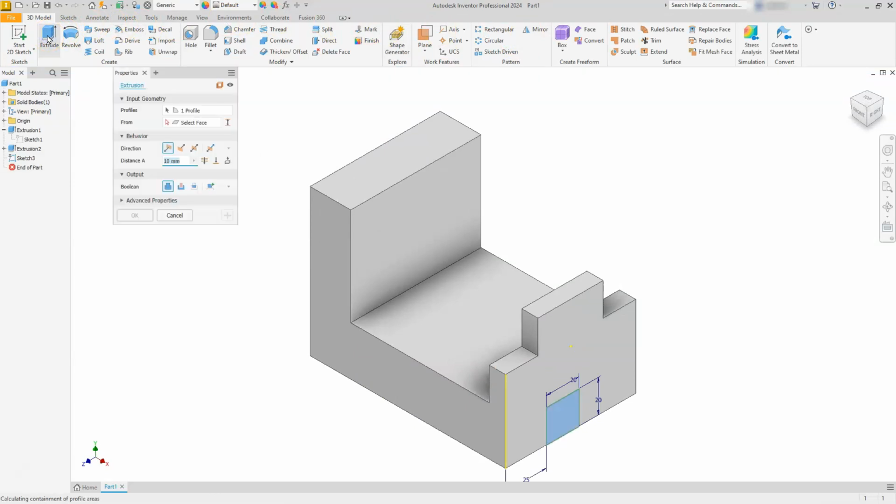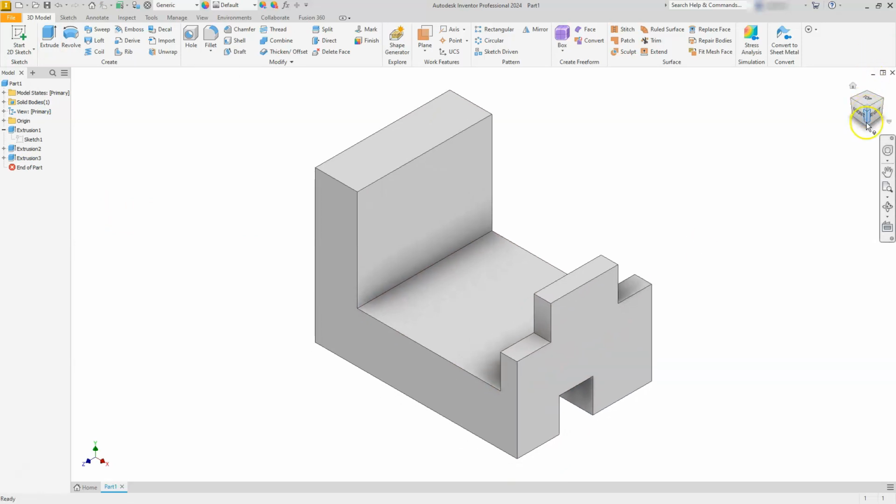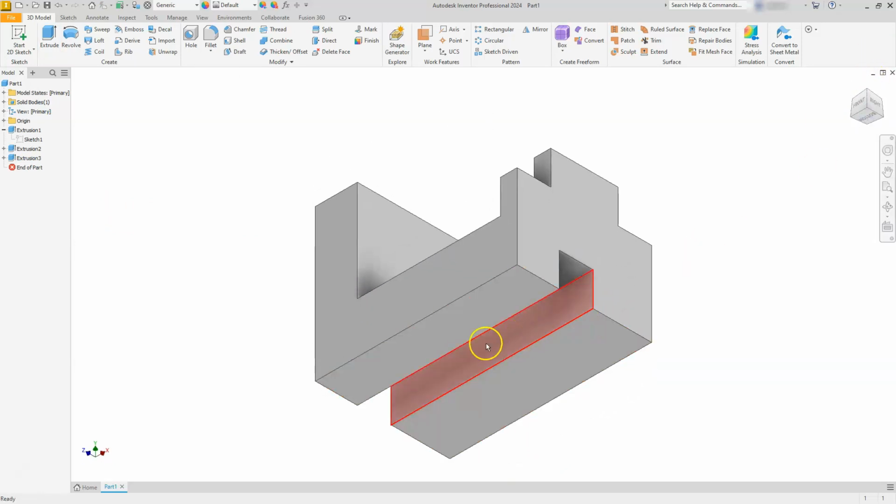Choose Extrude. And you're going to see that this is going to start building this and assuming that I want to go this direction. When I change the direction of this, so I'm going to flip it, you're going to see that this icon automatically switched to subtract. So now it's in a subtract function automatically for me. And then I can tell it that I want to go through this distance, right? So I can type in a distance. Or I can select this icon here that says, hey, send it through all of it. And hit OK. So now if I rotate around, you should be able to see all of this shape as it's cut through.